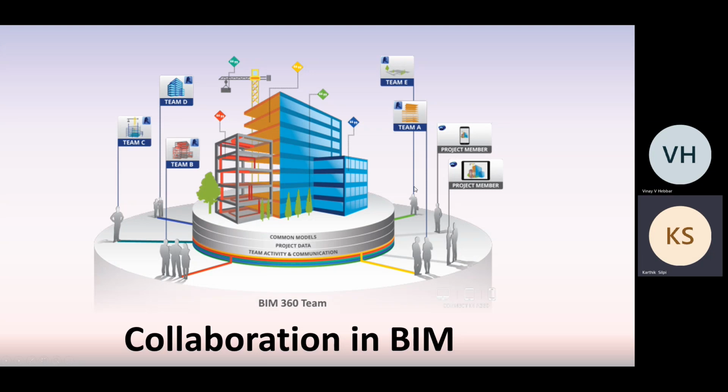Here, this is an image that demonstrates how BIM works. You can see there are multiple disciplines. Everyone is working on their own: someone is working on the facade, someone on structural engineering, someone on some other MEP services. They save the model in the central file. Whenever someone from this team has to access it, they can access it from the central file and work on that. So at the end of the day, everyone is going to save to the central file. You can see the project gradually being completed in full, starting from design to build and then operate also.